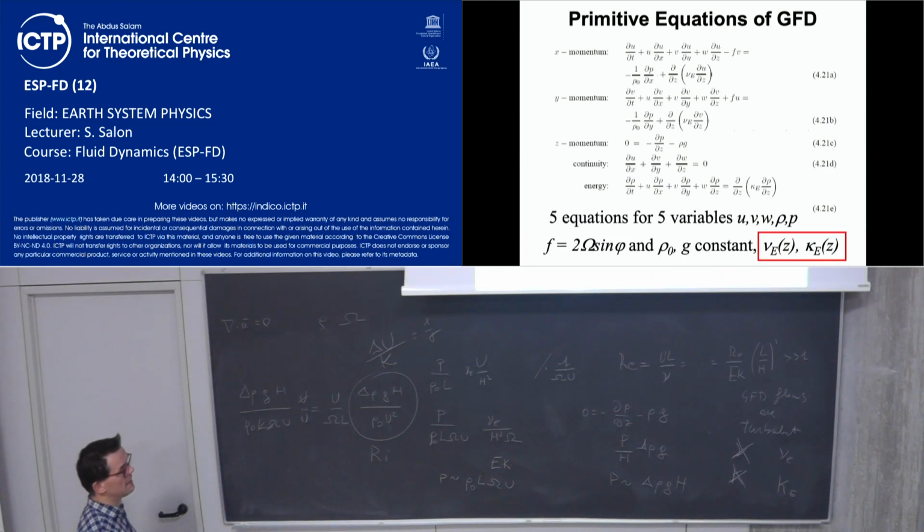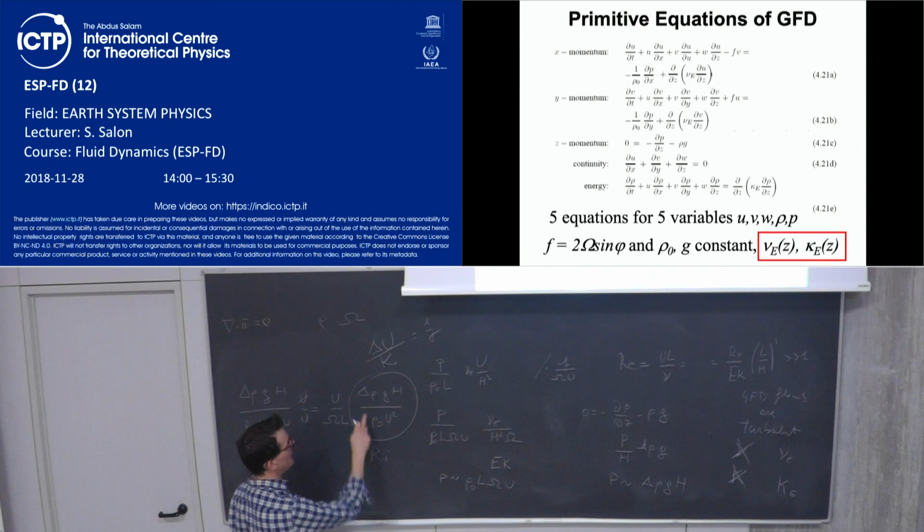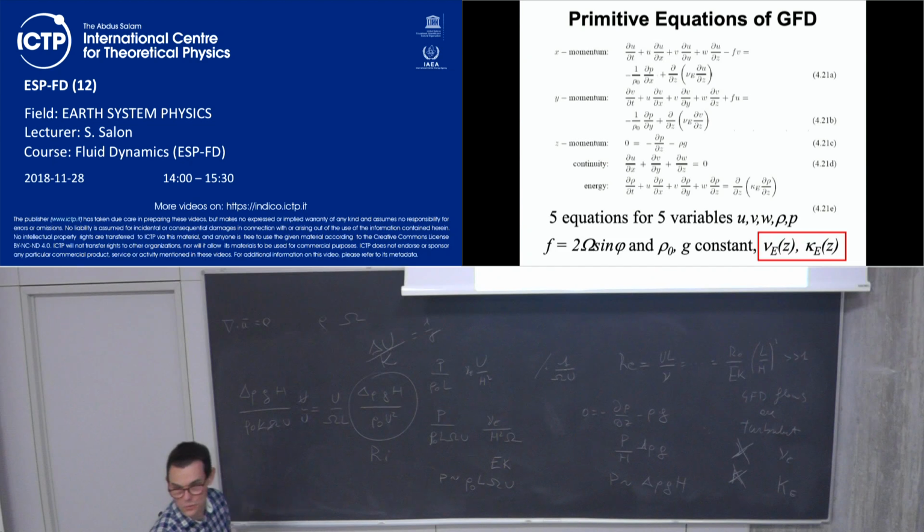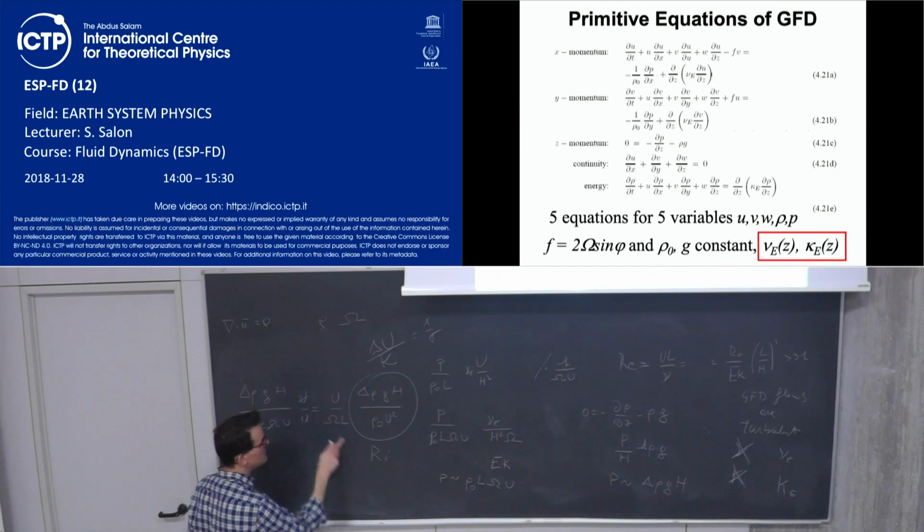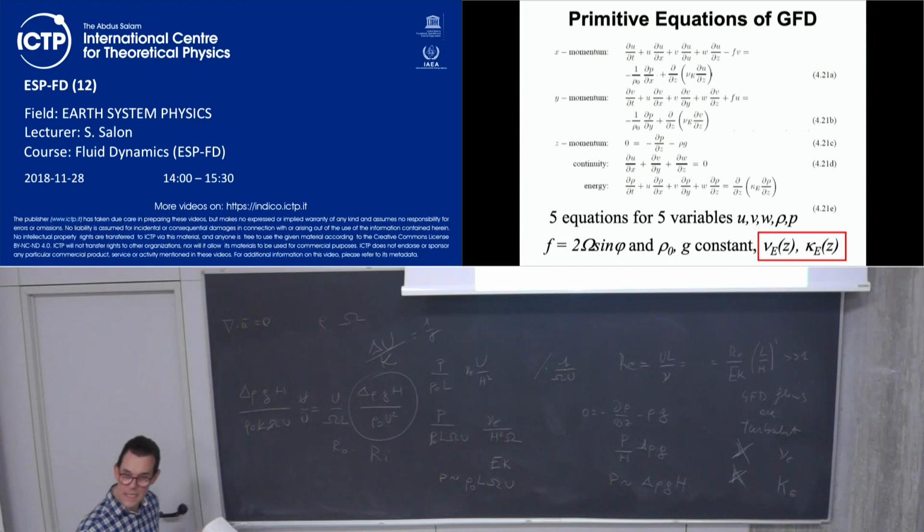makes the ratio between the potential energy related to the variation of density and the kinetic energy related to the fluid flow. So we can say that the ratio between the two expressions of pressure scales like the Rossby number multiplied by Richardson. So according to the importance of these different numbers, you can really tune the number and have different kinds of flows.